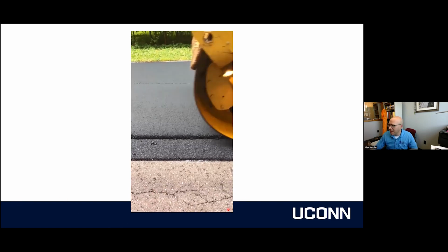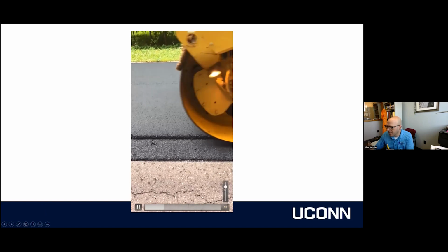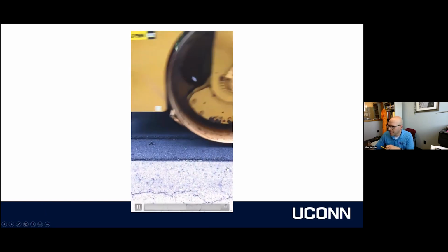Here's a quick video again of a vibratory roller going by. And what's really cool is if you look quickly there, because of the water, you can actually see the impacts happening. Whoops, I want to show that video again. Can't do it. So you can actually see the lines. Those are the impacts. And if you were to take a picture of that after marking about a foot out, you can find the ideal spacing, which is 10 to 12 impacts per foot.